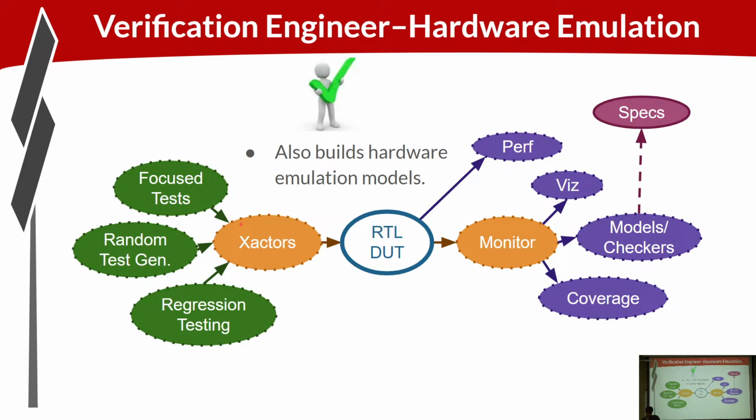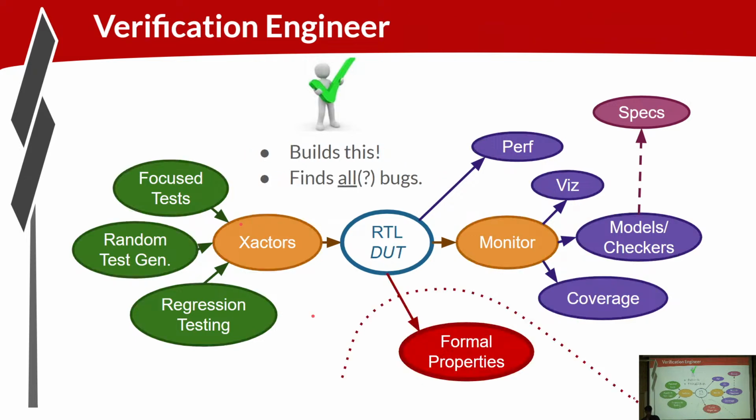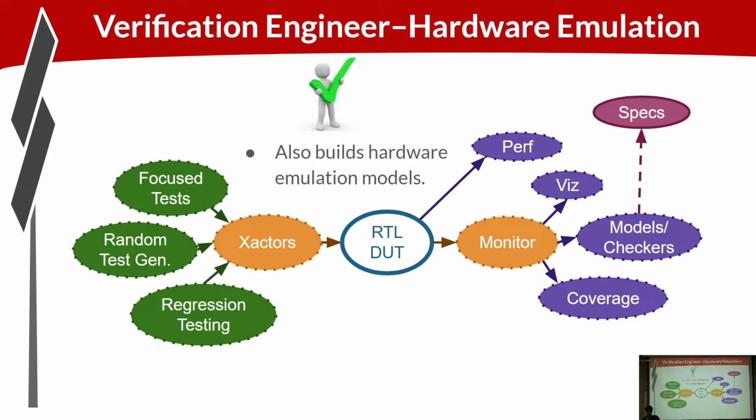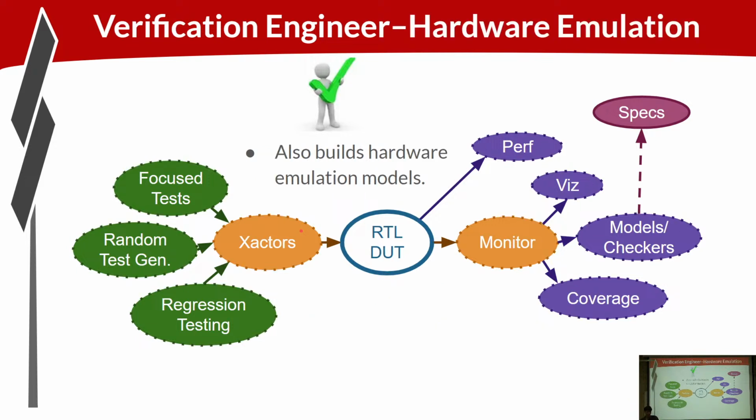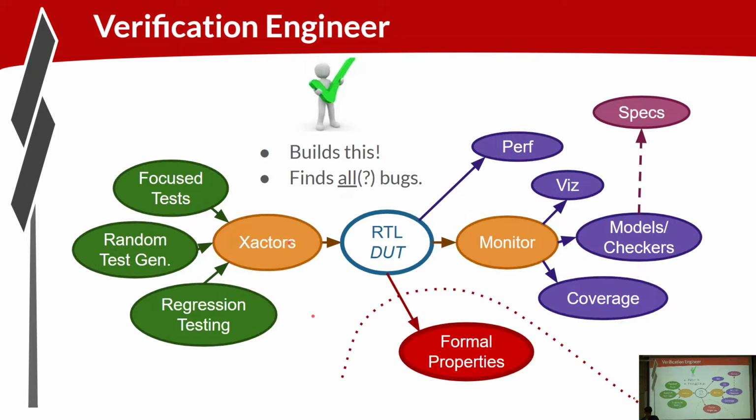But especially since the simulation-based environments generally come together sooner, the hardware emulation often, although it shouldn't be, is an afterthought. Often these components get developed in a way that's not friendly to emulation. So there may be some additional work to develop transactors that are appropriate in this environment. You can afford to do a lot more with the transactors and the monitor in simulation, since your simulation speed is limited by the simulation of the RTL anyway.